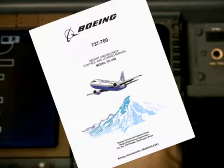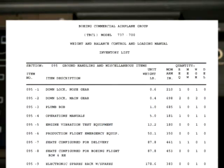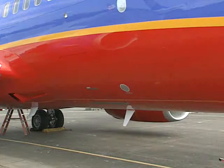An inventory list must be created that completely defines the contents of the airplane in its BEW configuration. One of the many documents that are delivered with a new airplane from Boeing is the Weight and Balance Manual. Chapter 2 of that manual includes an inventory list that documents the empty weight configuration of an airplane at delivery. Airlines should use this as the starting point for creating their own list that documents their own definition of the airplane's BEW contents. Prior to any weighing, an inventory of the airplane must be done.